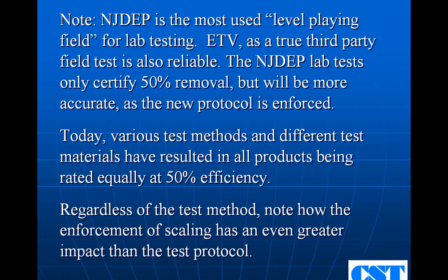Yes, but if the regulator took time to go look at the test, which they don't, and if they could understand all the mumbo jumbo of performance curves, et cetera, which they might not, even at the end of the day, if they came up with a number, yep, they can run 3 CFS, and they looked over at the certified removal rate of 50%, they would realize they're not doing apples for apples.